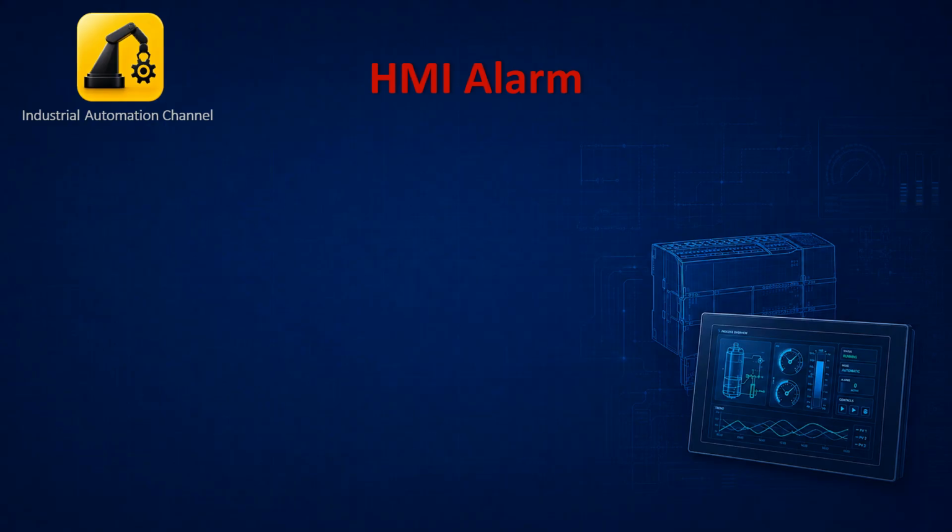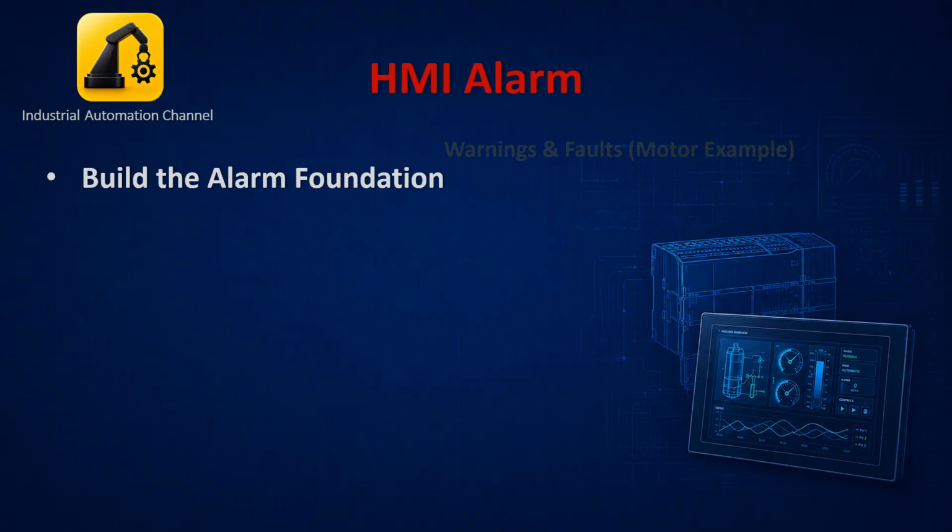That's why I made this as a 3-part series. In this first video, we'll build the foundation. We'll create the alarms for our motor example, decide which ones should be warnings and which ones should be faults, place them on an HMI alarm screen, and test them live.